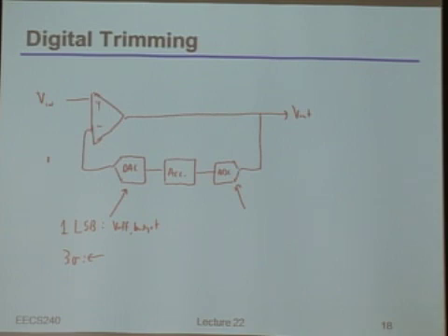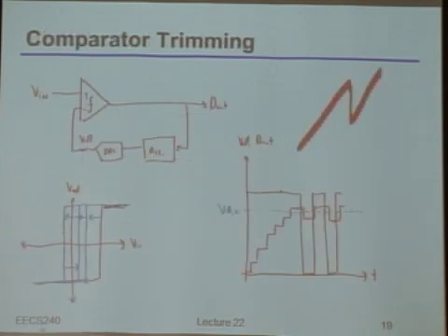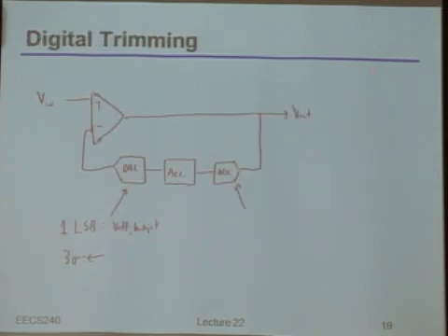Yeah, exactly. So we just convinced ourselves that we can offset cancel the comparator, which is our ADC. So you'd first offset cancel the comparator itself. Then you use that offset canceled comparator to cancel the offset of whatever thing it is you're trying to measure in the first place. Okay?